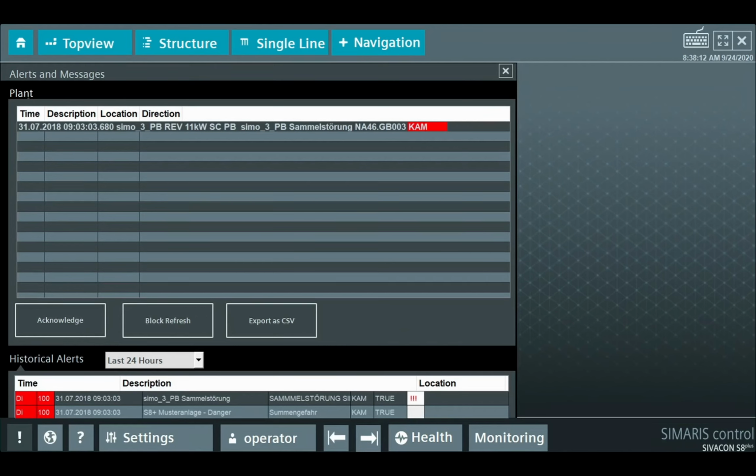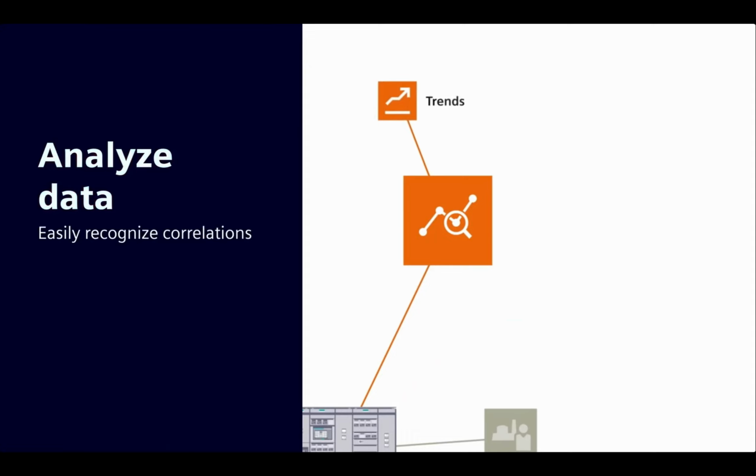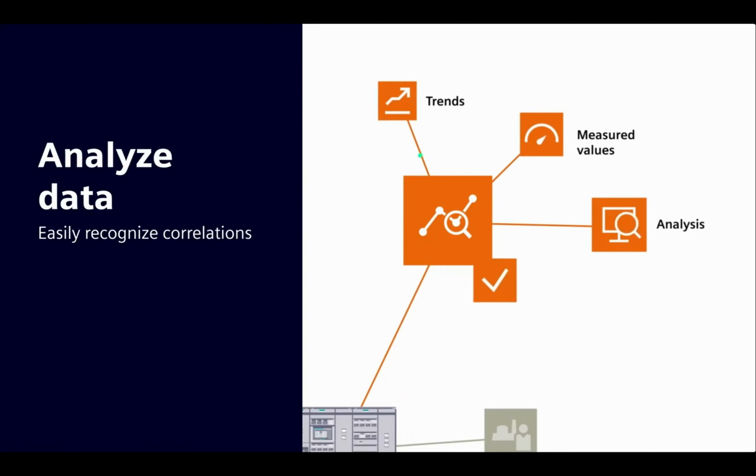Then we have a shunt. In addition to the A to D conversion, some algorithms calculate the current values, the current, and evaluate the data somewhere in the digital system, and we have the results of the current evaluation available to the user. And with this goal we go into condition-based maintenance, or even better, predictive maintenance with the help of continuous data analysis.